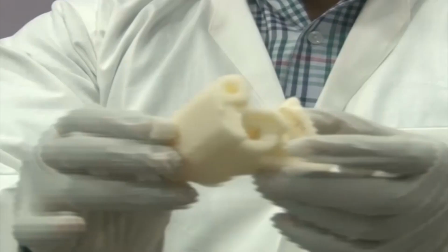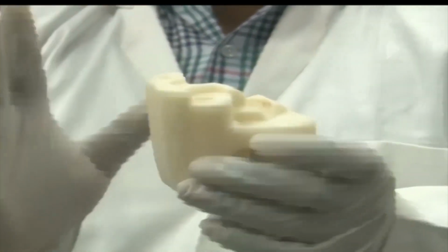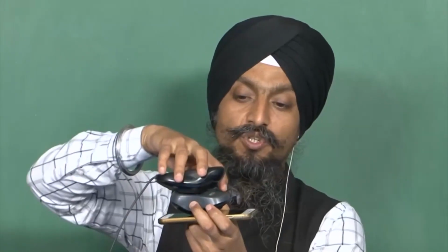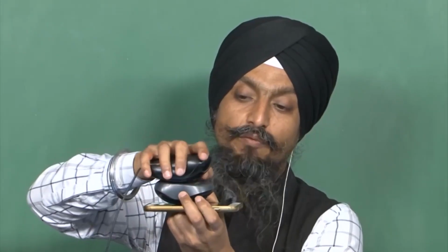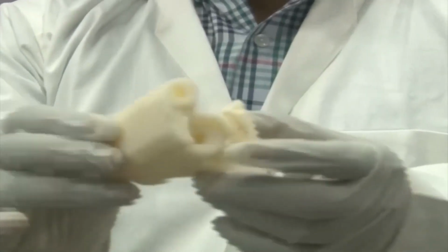In this CAD model, if you see, we use the everywhere command, okay, because it is profiled everywhere, not just touching the bed. For instance, this is the model, like I just said, it is touching the bed. If there is another thing manufactured here, the portion in between here is not touching the bed, but it would provide support here as well, because it has to produce this as well. So in case of touching bed, it will provide support here only. In case of everywhere, it will provide support here as well. So for complicated models, we use the option everywhere.